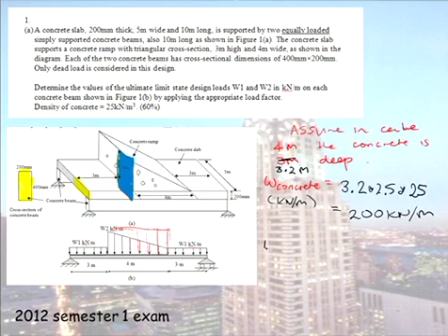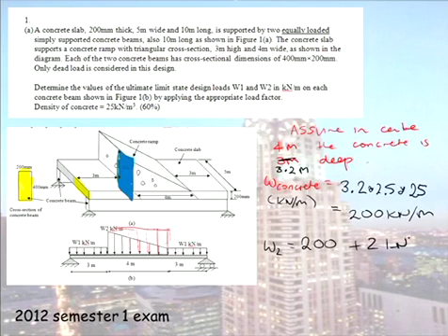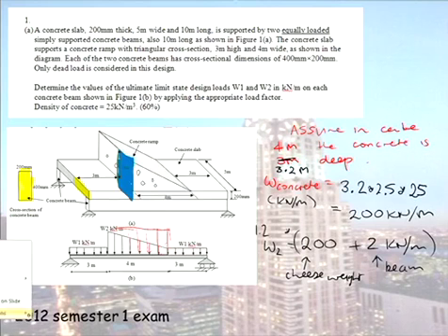So therefore, what is W2 equal to? It's equal to my 200 plus the weight of the beam here, which we said was 2. That's the beam weight, and that's the, I call it the cheese weight. So that's the value. We then multiply that by 1.2. So W2 is equal to 1.2 times 200 plus 2, and that is a value of 240. I can't read this writing there. What is it? 242.4. Excellent.